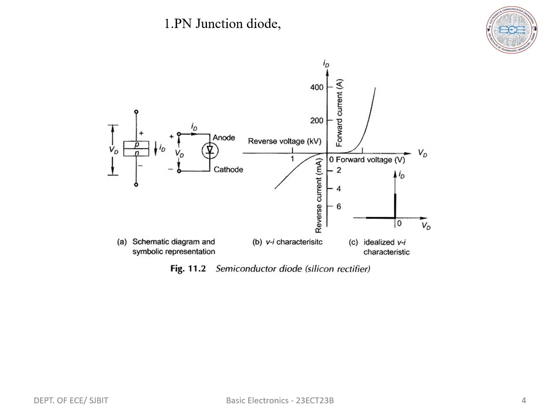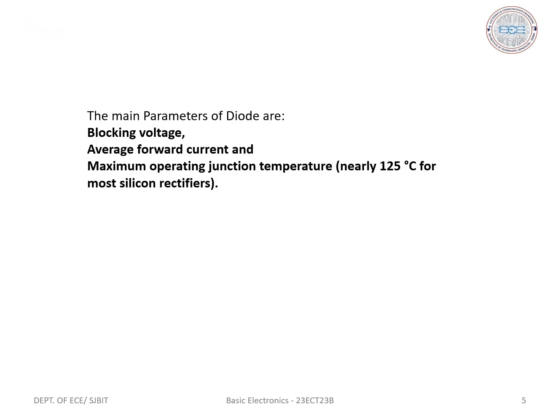Next, we will start with the main parameters of the diode. The main parameters are the ratings of diodes, which are important in circuit design and component selection. Some of the widely used diode specifications are knee voltage, or forward voltage, or cut-in voltage. It is the voltage applied across a forward biased device, the voltage at which the current through the junction starts to increase rapidly. The knee voltage or cut-in voltage for silicon is 0.7 volts and for germanium is 0.3 volts.